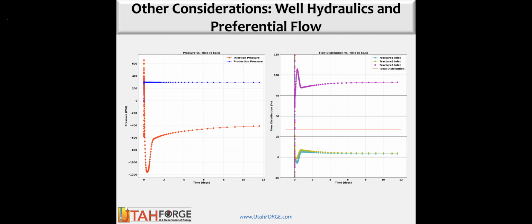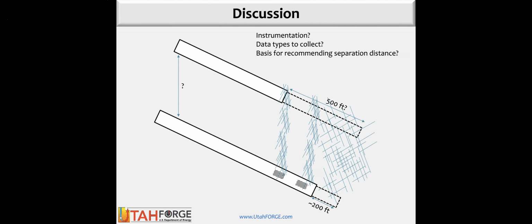But the important part here is that open hole zone, without having any pressure drop across the perforations, is taking essentially 90-some percent of all the fluid going through just that lower zone. So you're exactly right, Nicole, how we parameterize and design the completion can potentially have a very strong effect on how we get flow through the reservoir, especially as we get more and more clusters along the well.